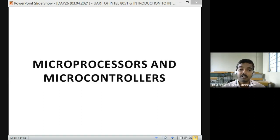At the end of the session, we also discussed how to calculate the count value to be loaded. We should not put the desired count directly into the count register, because it will not generate the interrupt for the count for which we are writing the program. We have a calculation to load the count value. Yes, very good: maximum count value in the particular mode minus the desired count value plus 1. That's the correct answer.